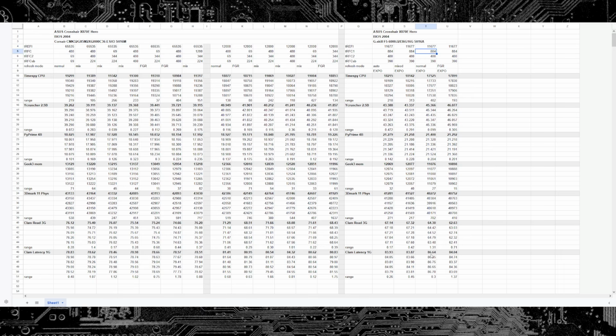And so that means the worst case scenario for latency in normal mode is kind of worse, especially because normal mode uses a much higher TRFC value than TRFC2. And mind you, these timings right here, this isn't G.Skill doing anything with the Expo profile. This is just JEDEC values scaled up to DDR5 6000.